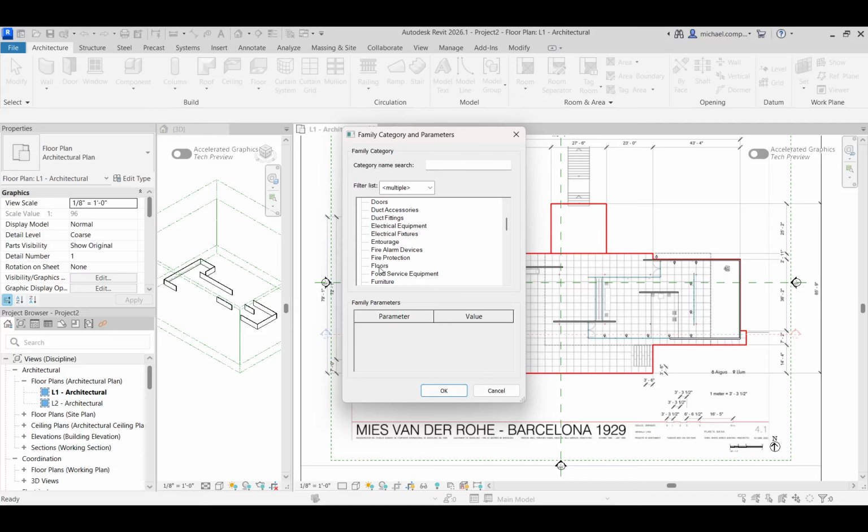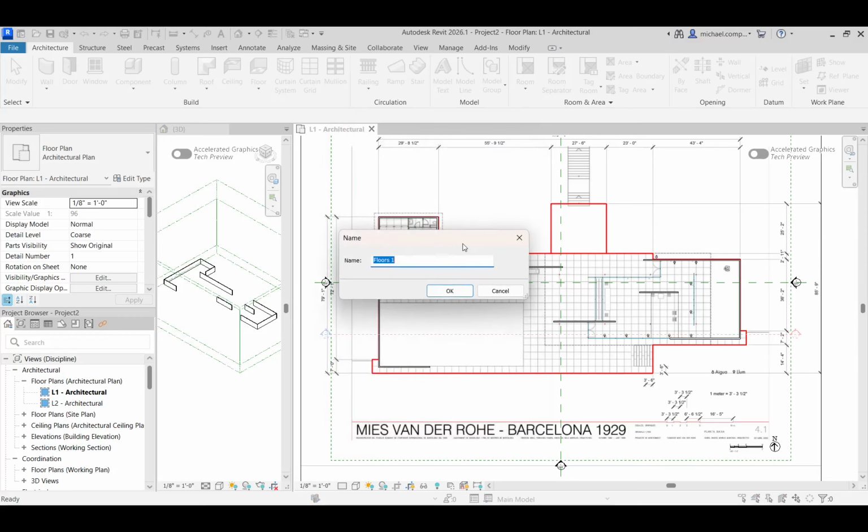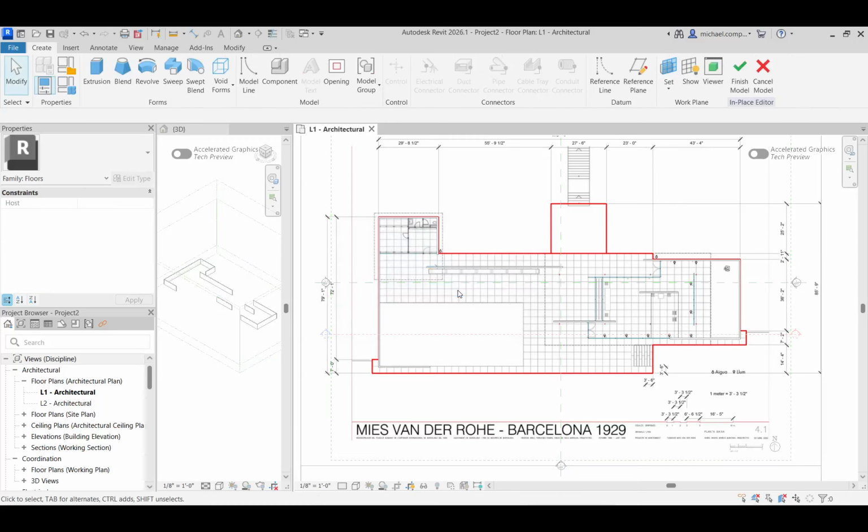And we can get into plinth versus floor versus tiles on slab or, sorry, on grade or whatever. But for today's purposes, I'm going to use a floor tool or floor family, excuse me, and then hit OK. And I'm going to again use the extrusion.